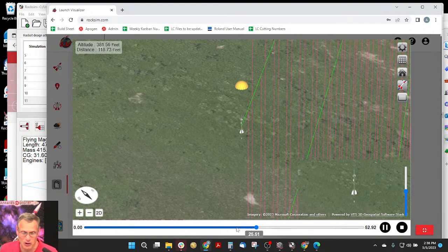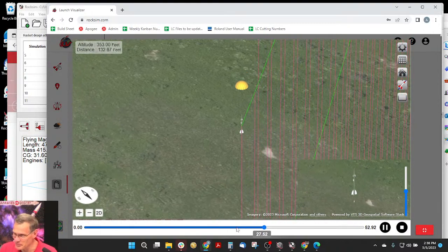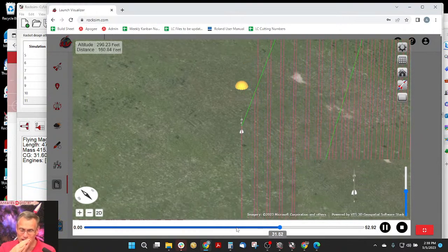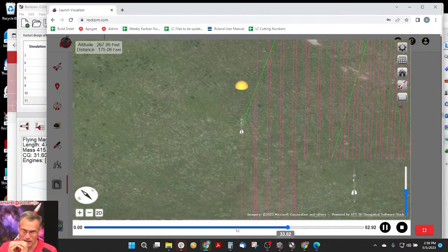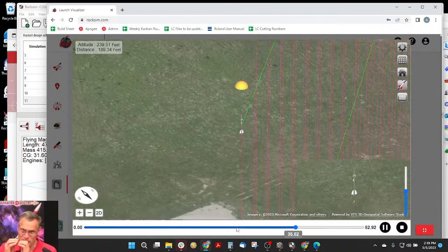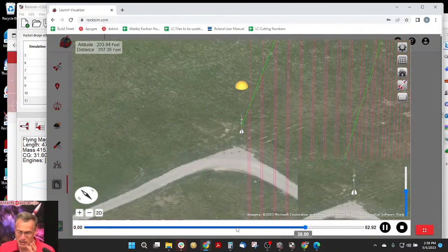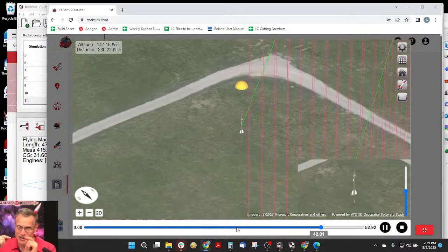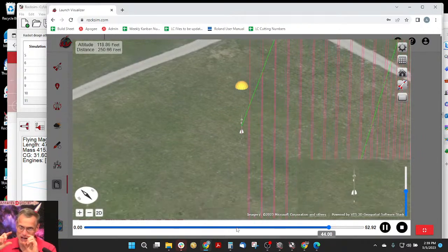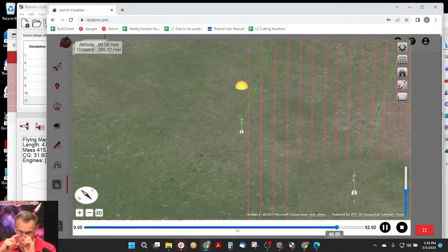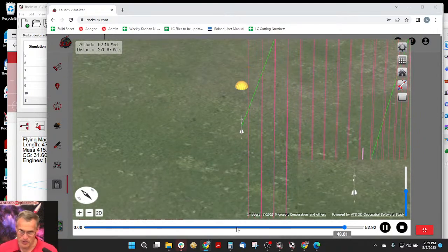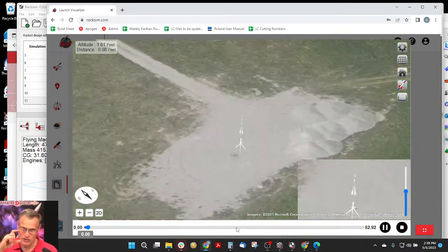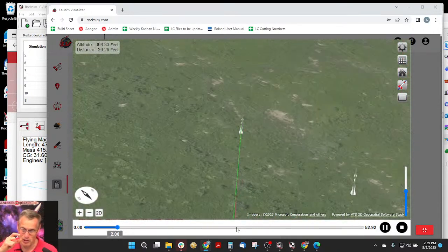So it was a little bit more convoluted than I thought, but it was simple math. You just have to watch your delay times, and in order to get everything to happen at the same time, the ejection time for the parachutes in the pods has to match the ejection time in the core. And you have to remember that to get the ejection time for the core, it's the standard delay plus the burn time.